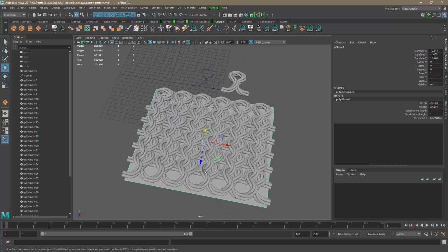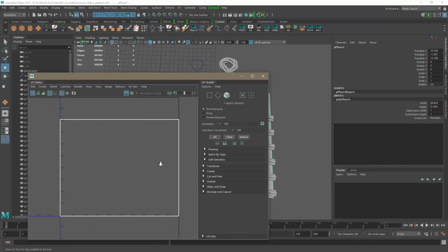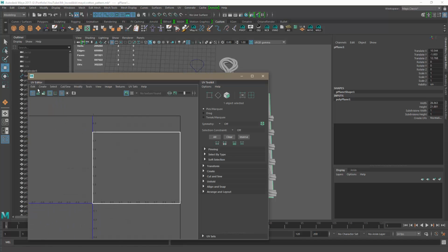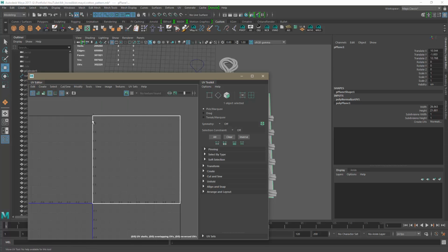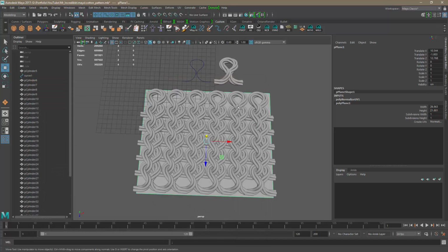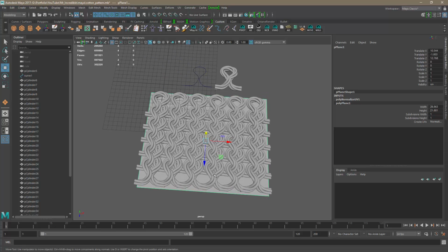And now first of all, let me check the UVs of this object. Yeah, they're not normalized, so let's go to modify and click on normalize. So now I have nicely distributed UVs on my plane, and that's pretty much it.